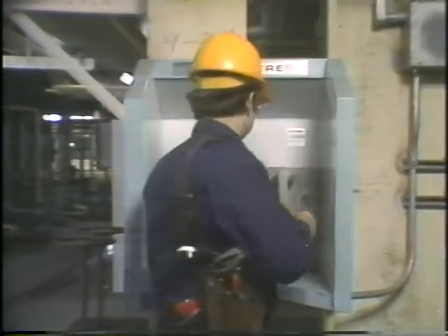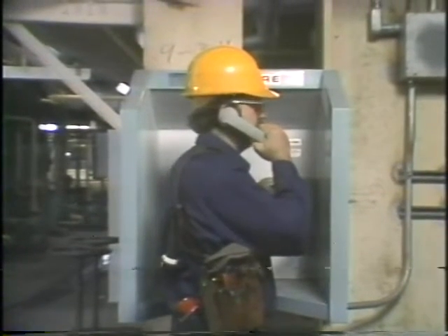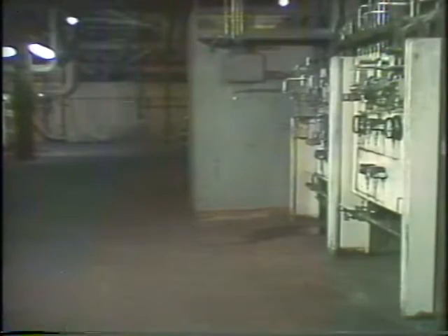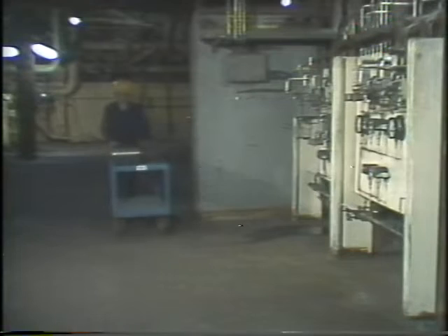He'll also need to call the operator to tell him that there is, in fact, something wrong with the transmitter, and that the operator will have to keep the system in manual until the transmitter's fixed. So far, we've seen Bob observe the system, then make a diagnosis that a particular instrument was bad. He was able to test the transmitter by valving it out. And sure enough, the test confirmed to him that there was a problem with the transmitter. So now he'll have to make more tests to figure out what's actually wrong with the transmitter.